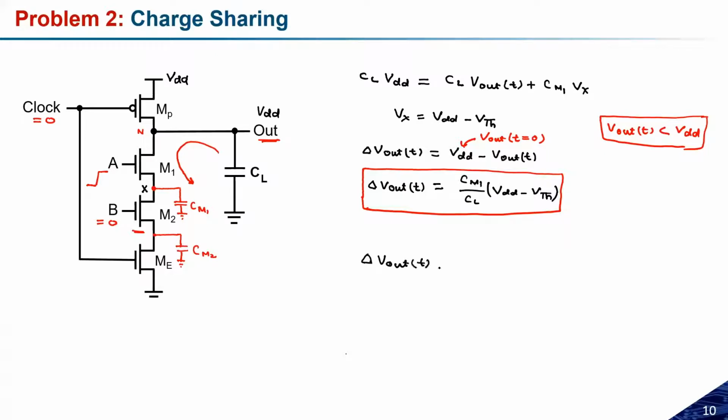at T will become VDD. Yeah, because it is decreasing. Because the charge that was initially there is decreasing, we can keep a minus sign here also, whatever the VDD was. This is simply the divider formula being applied: CM1 divided by CL plus CM1.